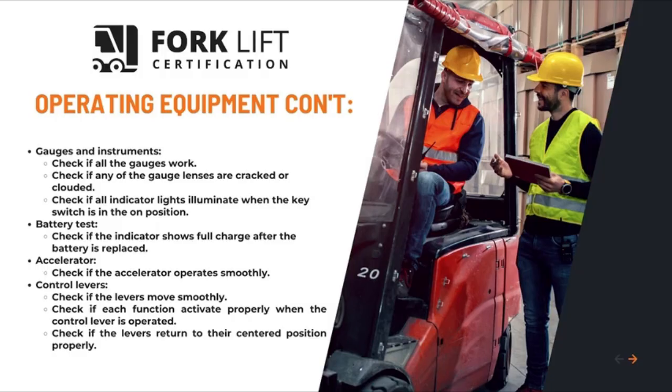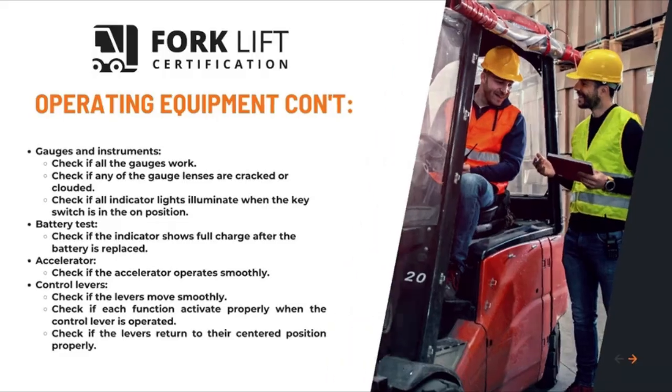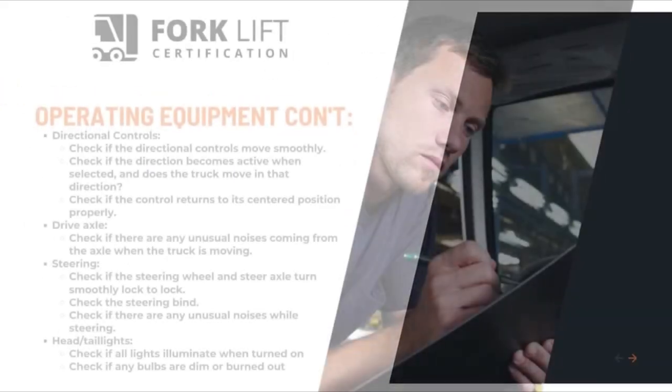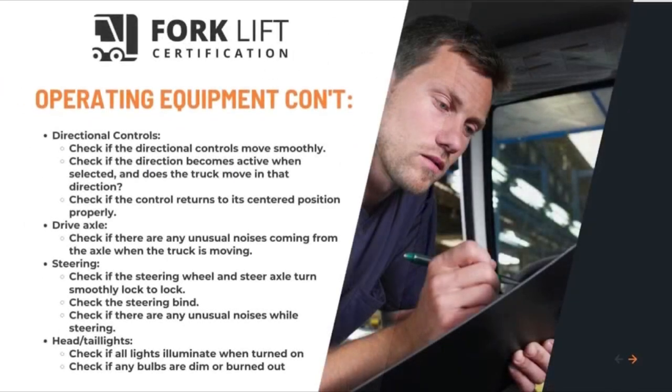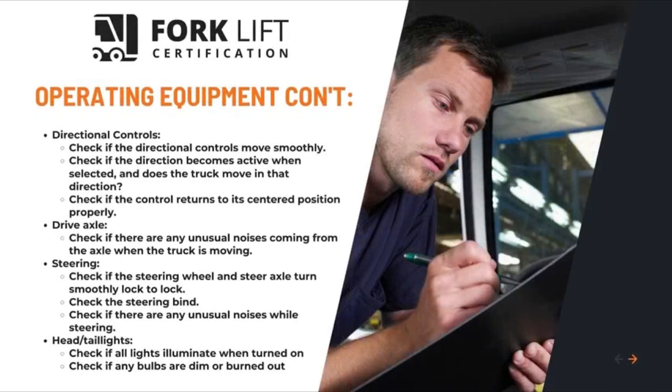Check if the levers return to their centered position properly. Directional controls. Check if the directional controls move smoothly. Check if the direction becomes active when selected, and does the truck move in that direction. Check if the control returns to its centered position properly.